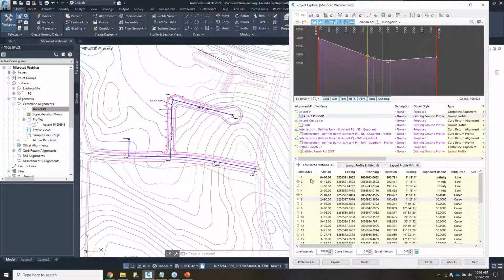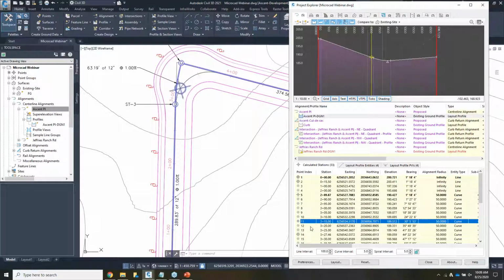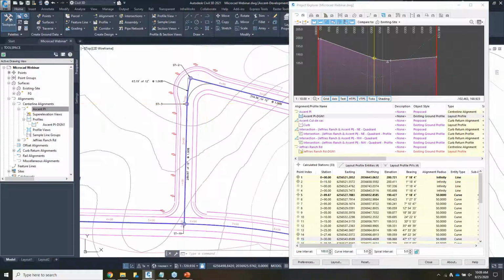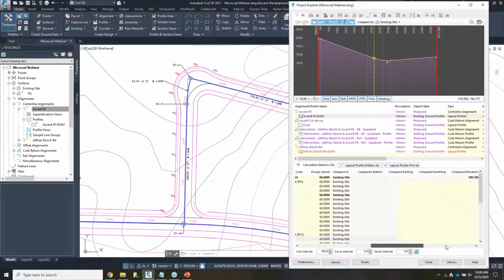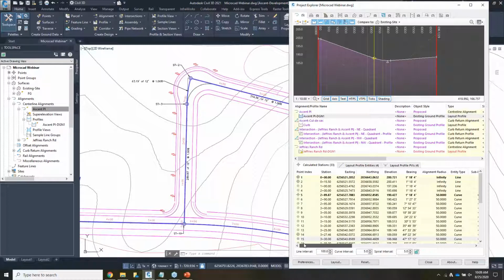And if I hit the Control button, it tells me where I am in plan view as well. So very, very powerful in knowing where I am in the plan view as well. So just by toggling the Control button on the keyboard gives you a preview of where you are in the drawing, as well as up here. The tabular view at the bottom here, you can always change what you see. So there's plenty of information here, and that might be a little bit overwhelming or unnecessary. So at the very bottom, you can control what you see.